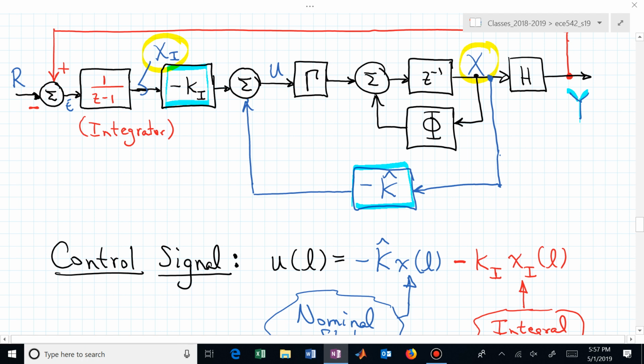We've introduced one more Z, or one more pole, in our system, and so we have augmented our state space representation. Originally, that z to the minus 1, that's a bank of z to the minus 1s. Phi is still 10 by 10, possibly. So maybe we had a 10th order system. Now we've augmented it. We would now have an 11-dimensional augmented state vector.